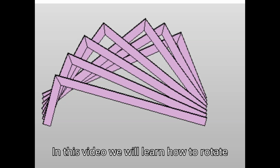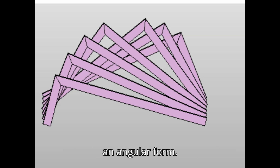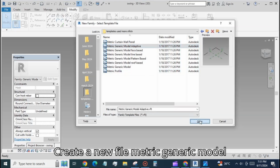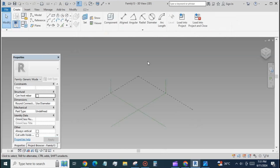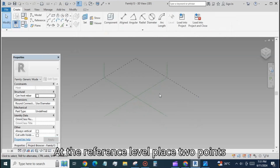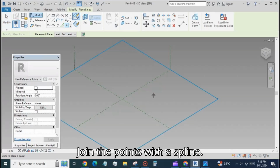In this video we will learn how to rotate and at the same time change the shape of an angular form. Create a new file, metric generic model adaptive. At the reference level place 2 points and hold them and make them adaptive. Join the points with a spline.